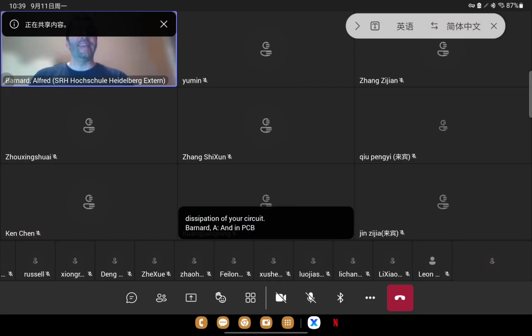And in PCB design, this is a very major theme going throughout your designs, that you will have to know how much current is running through any specific trace, and how much current it might expect to see even in a short circuit.